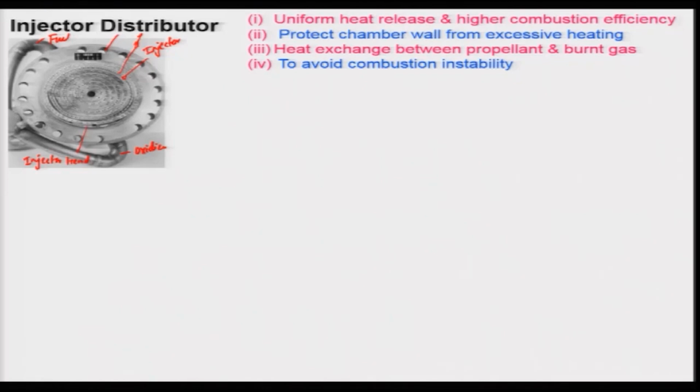And besides this, there should be proper heat exchange between the propellant and the burnt gas. That means whatever propellant is being injected and atomized or vaporized should receive heat well from the burnt gas, such that you can have easier, faster vaporization.